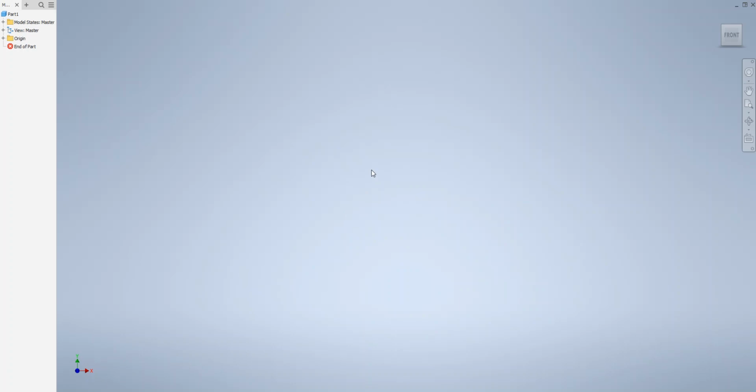On the left side there is the project browser. You go to the plus button next to the word origin. Click on the plus button, and that enables you to select one of the planes. On the top, there's a YZ plane, usually a vertical plane. XZ plane is again a vertical plane. There is an XY plane, a horizontal plane, looking top down. And at this time, I usually go to YZ plane, but this time I want to select XZ plane.